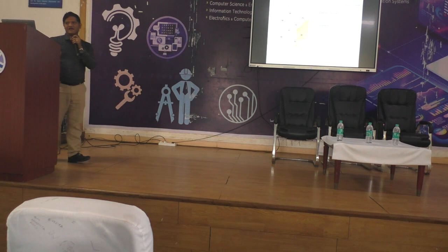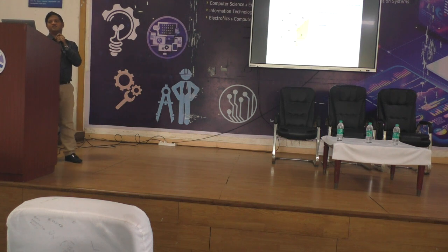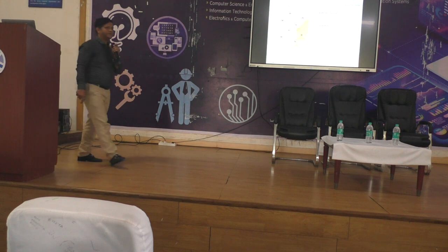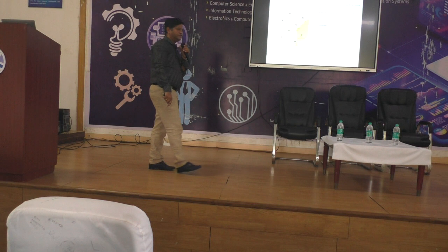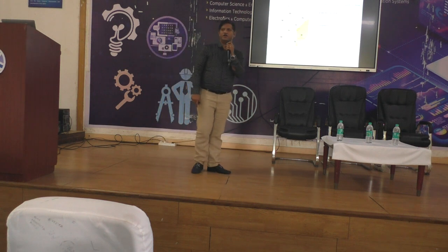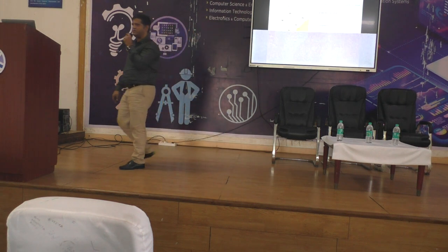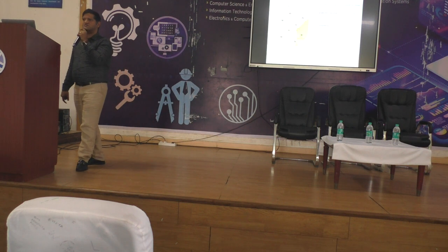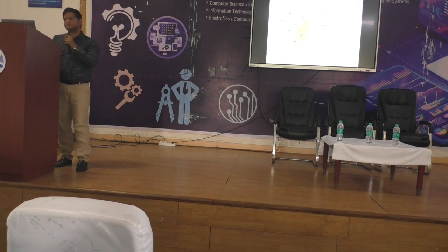See the volume, see the axis. So in region 1, the products are in high volume, with low customization and low complexity. That means the products which are very simple and which we want to go with mass manufacturing, there we can go with the conventional manufacturing process. The additive manufacturing process is not economical.